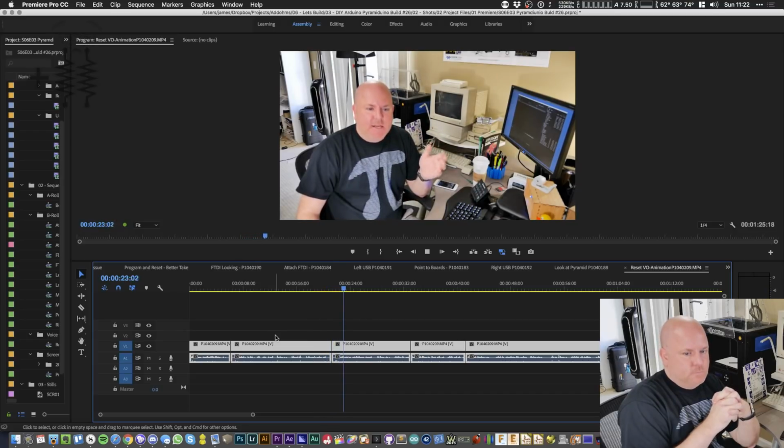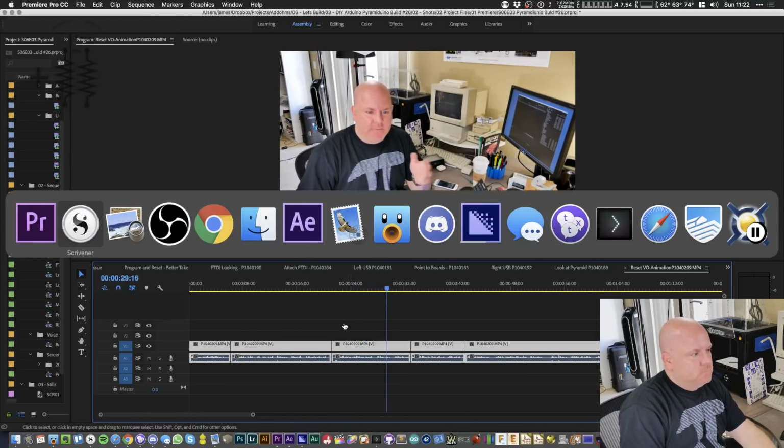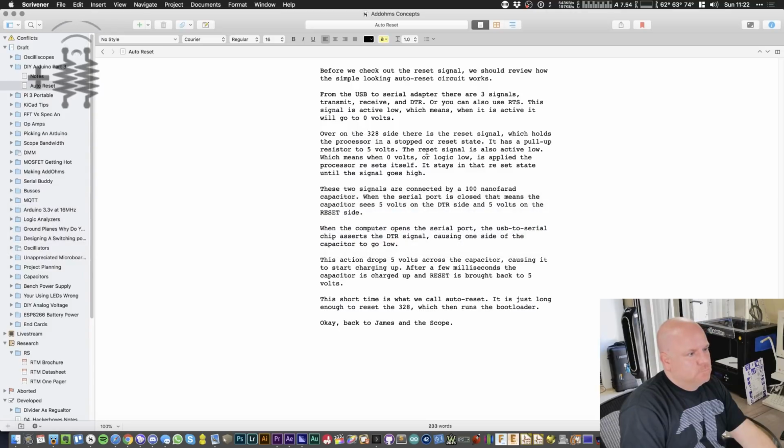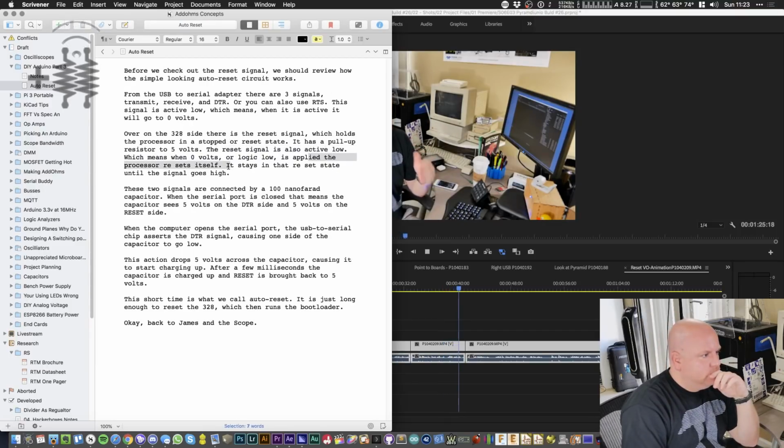Over on the 328 side, there is a reset signal, which holds the processor in a stopped or reset state. It has a pull-up resistor to 5 volts. The reset signal is also active low, which means when 0 volts or logic low is applied, the processor resets itself. It stays in that reset state until these two signals are connected by...